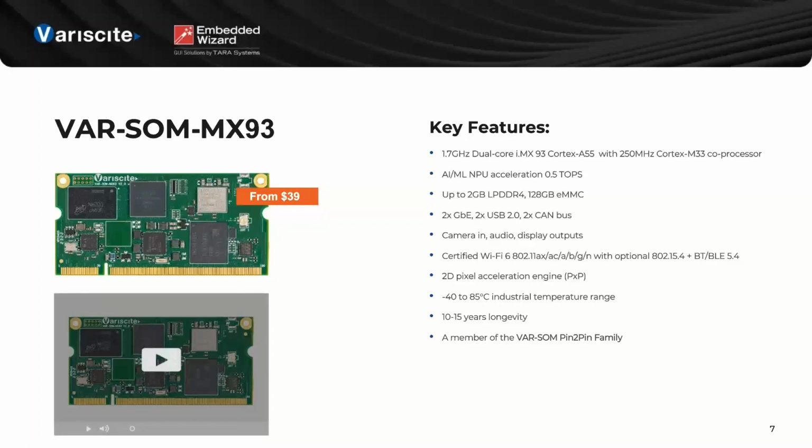There are 2 gigabit Ethernets, USB ports, 2 CAN buses, the camera input, and audio, of course, granted through the Wolfson WM8904, and you have display output. In our evaluation kit, we provide a sample LVDS. The SOM itself comes with Murata Wi-Fi that is capable of also ZigBee optionally.